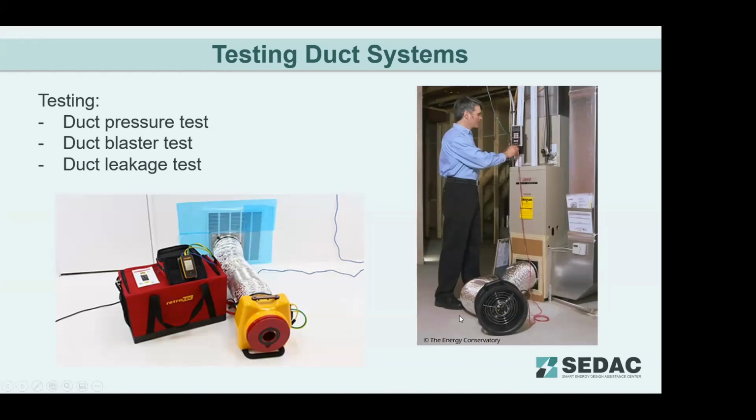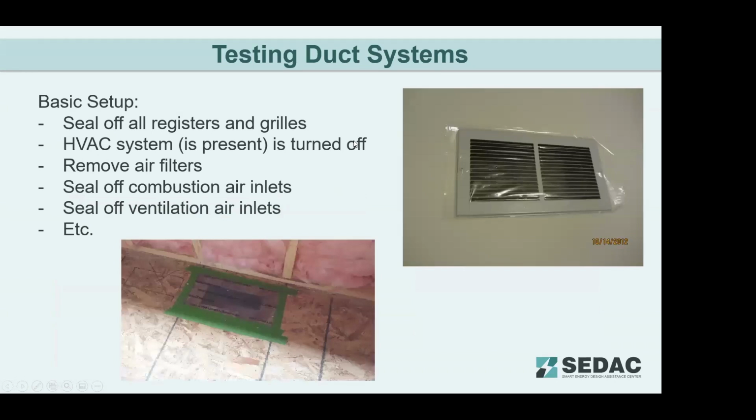You've got a fan that's going to either pressurize or depressurize the system. You seal off all of these supplies and returns, bring the system up to a specific pressure, and then measure the leakage rate, and hopefully compare it to make sure it passes or fails to your design, your pressures.